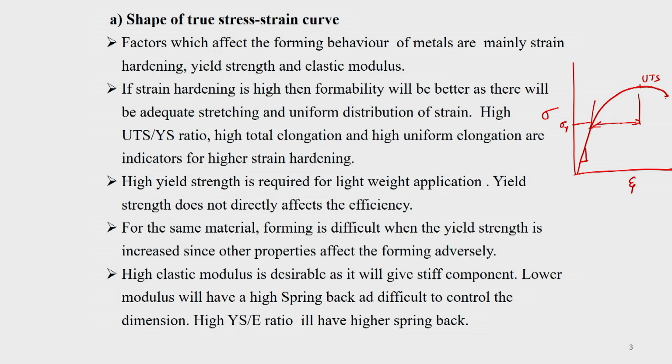And high elastic modulus is desirable as it will give a stiff component. So, lower modulus has a high spring back effect and it is difficult to control the dimension. So, with any material with a lower Young's modulus value, stiffness value, it is very difficult to control the dimensions. Okay, but with a higher one, though you may need higher stresses, you can control the dimensions